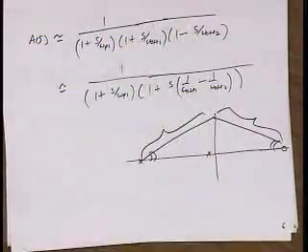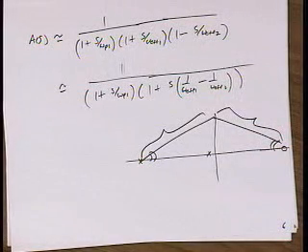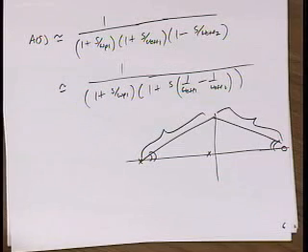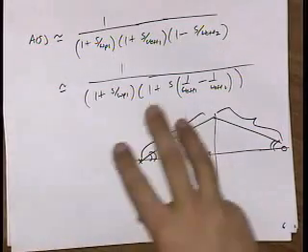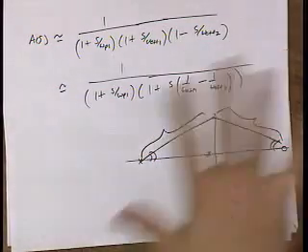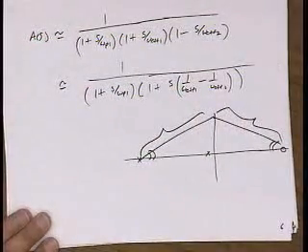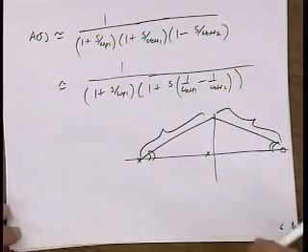And that's certainly the case with the amplifier that you looked at for your homework. There you have one non-dominant pole, and all the other poles and zeros are at much higher frequencies, on the order of fractions of omega t of the device. And so if you're designing an amplifier feedback system, you only have to consider the effects of the first non-dominant pole. The dominant pole, of course, is by design set by your load capacitance in the folded cascode amplifier.